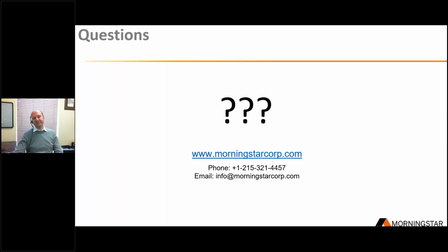Can you charge lithium iron phosphate batteries? Yes. Morningstar has a pretty sophisticated program in place called our Energy Storage Partners Program. You can find that on the website, and that is also managed by both a combination of the marketing team as well as our applications team. And the ESP program provides specific battery set points that can be loaded in just the way I spoke about to provide you manufacturer approved, agreed upon charge settings for a variety, if not the majority of the leading lithium ion or lithium iron phosphate batteries that are in the industry.